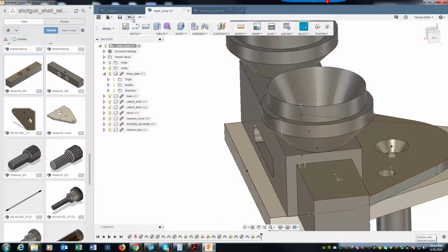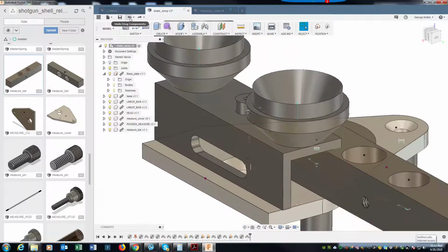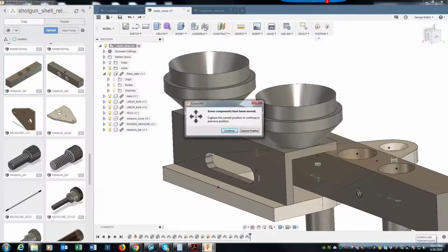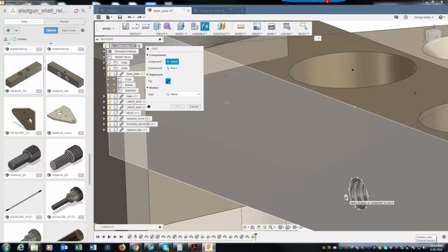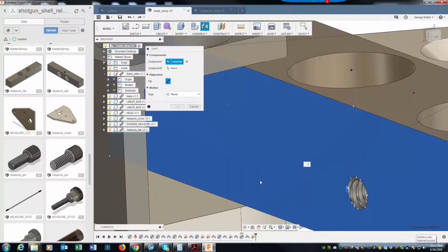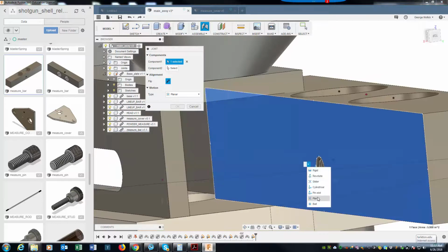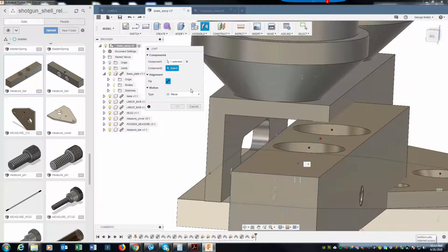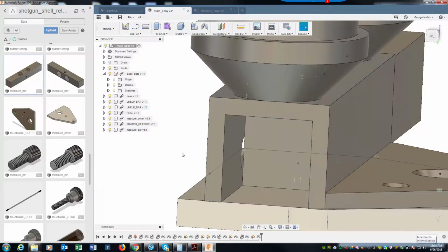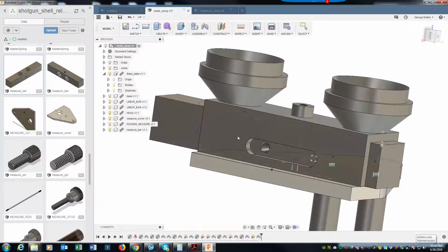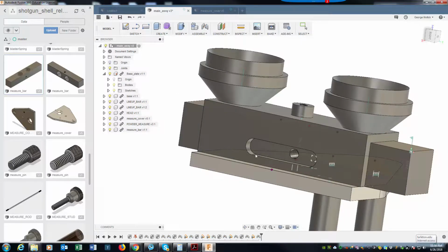And just in case you didn't see that, let me do that again slower, because that wasn't exactly obvious. So when I put that joint on, instead of picking the face, because this thing likes points, this is what I'm doing. I'm going to capture this position. So when I put this planar joint on, instead of picking the face, I'm going to make sure that I get this face, that surface there. And I want to make sure that I pick that as a planar joint when I do. And then I can come in here for the second, and I can pick this center of that hole. And those two points then are the points that it's going to, there you go, meet as planar. Okay. So I can do that.